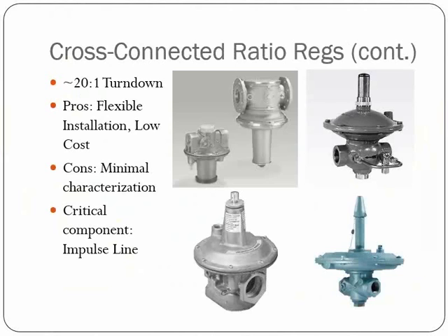If we think about if anything were to happen to that impulse line, or if there's any kind of moisture or debris that would get in there that would affect the changes in pressure, that would be a huge headache from a maintenance standpoint and maintaining your air-fuel ratio control on the system. So impulse line here is critical for these to operate smoothly and effectively.